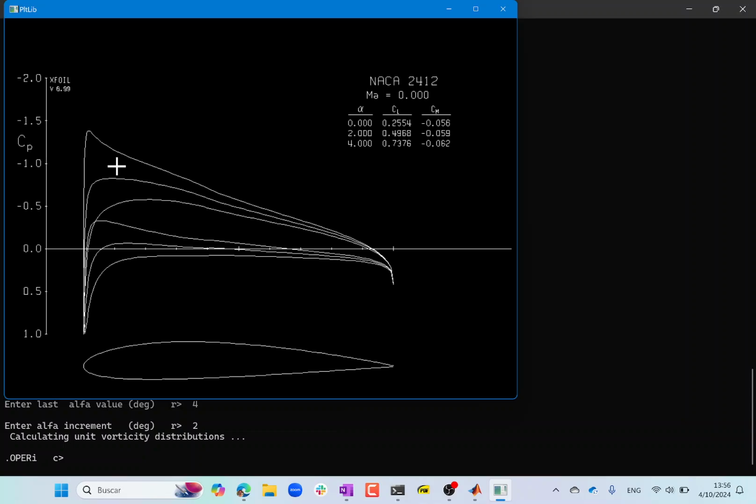Yeah, so if the ratio, if both numbers are the same sign, which right now is 1, and the CM is about a quarter of CL, then you're right at the end. So think about that formula, right? Yeah. So here you probably want to make the angle of attack lower, because right now your problem is they are not the same sign. Your CL is negative.